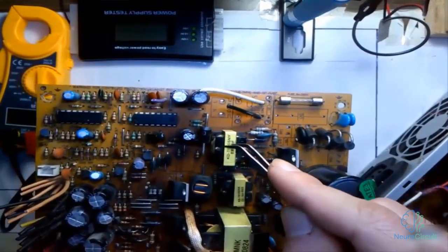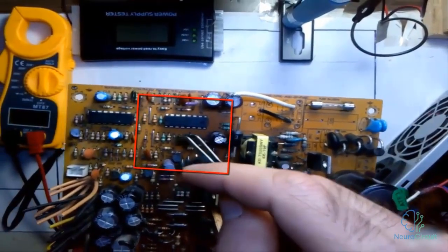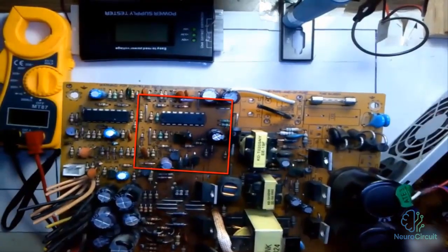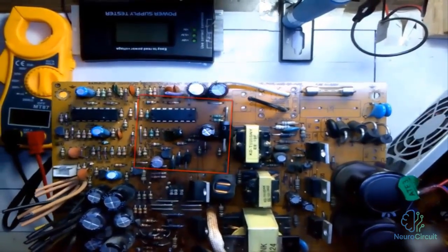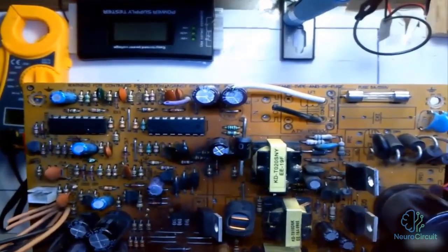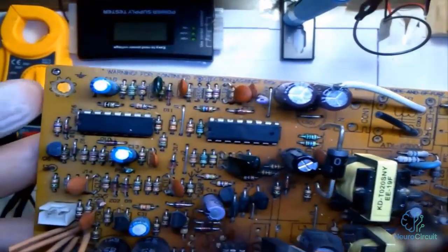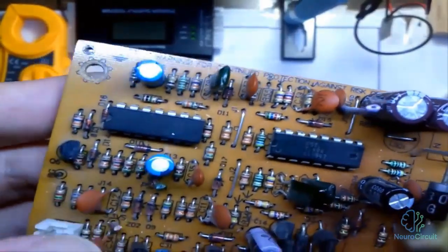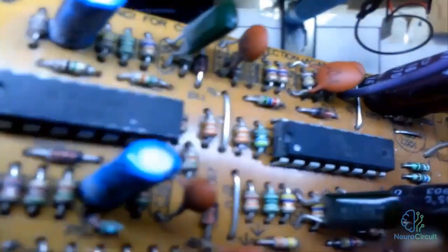This standby circuit is connected to a control circuit, which is also the circuit that actually allows you to turn the power supply on and off remotely. The control circuit is usually connected to a wire. In fact, it's connected to a green wire, and that's why we pulled out the green wire from this power supply for repairs. But its place is still there, and I can show you.